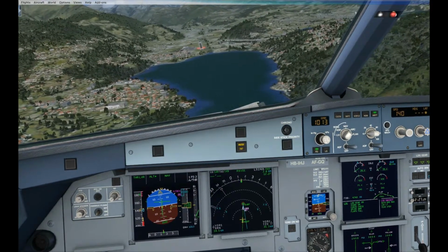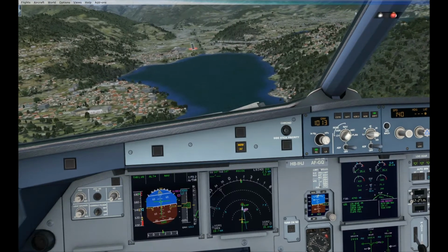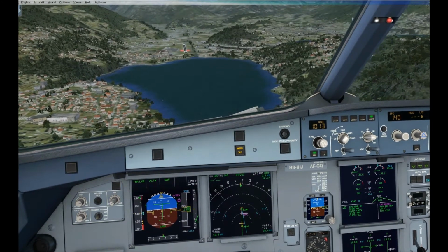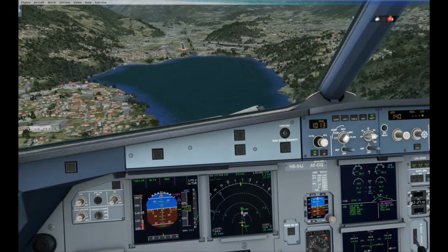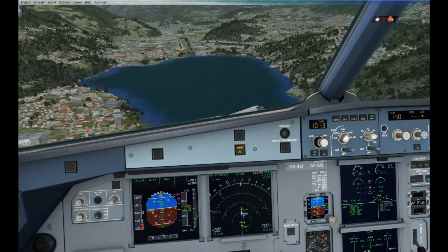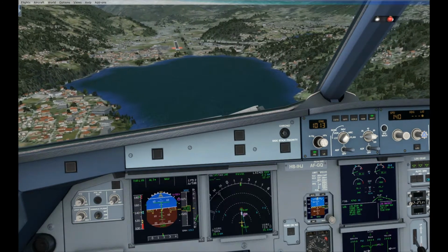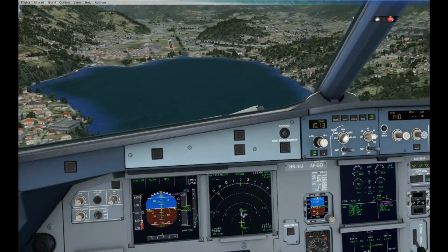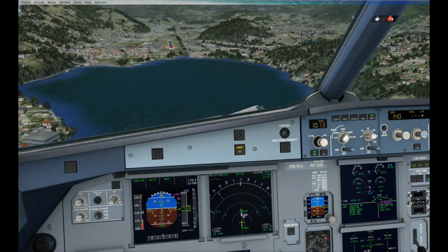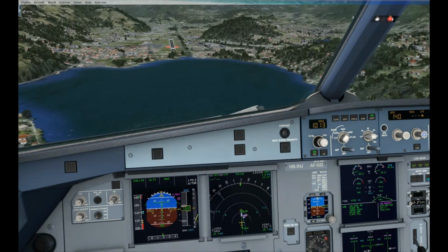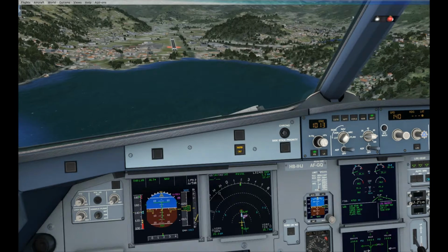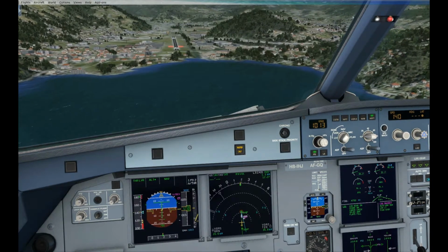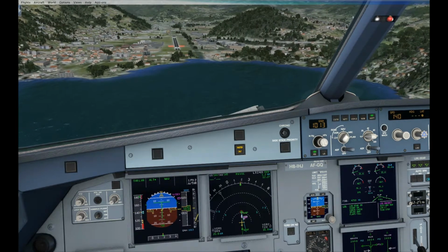I need to touch down as near the end of the runway as possible to give myself maximum landing capability. 140. Full flaps. Gear down. In the simulation you'll see there are trees just in front of the runway. I also have to clear that obstacle. Approaching 01.